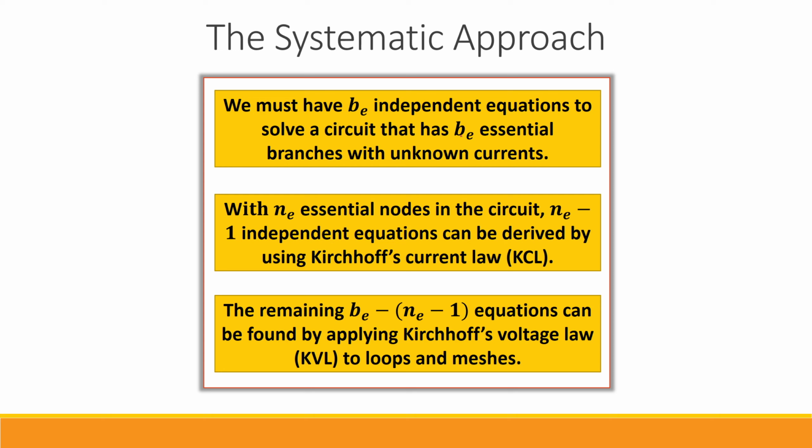For a circuit with B_E essential branches, so pay attention, this needs to be essential branches, with unknown currents, we need B_E independent equations to solve it.